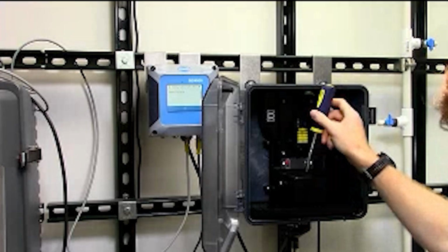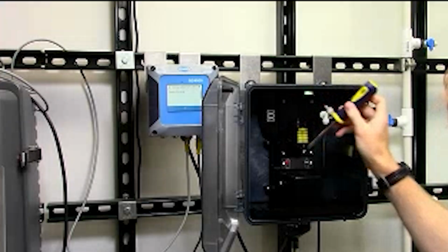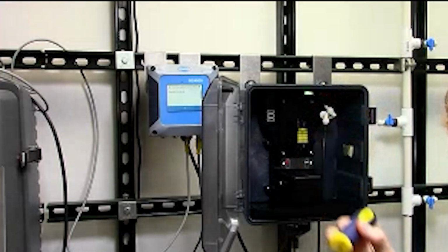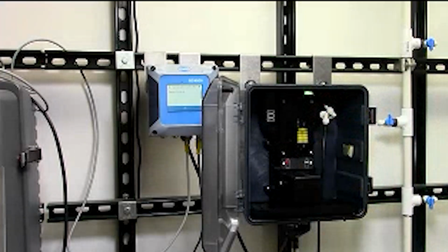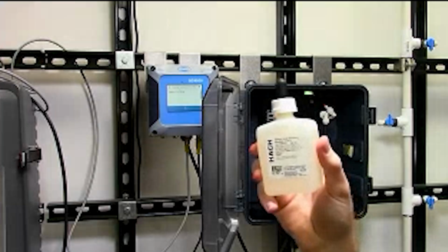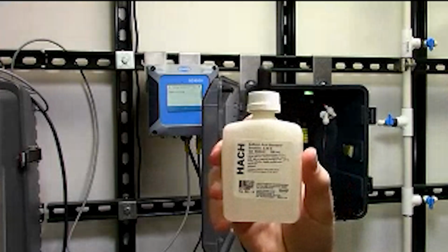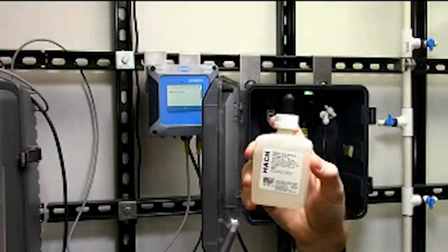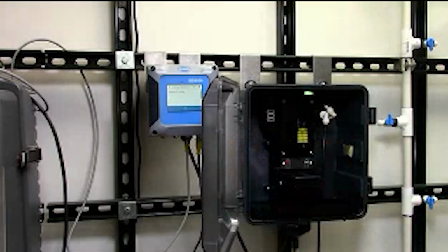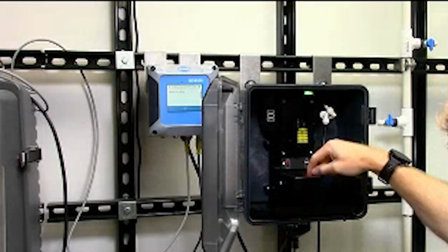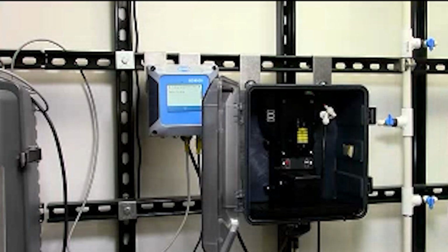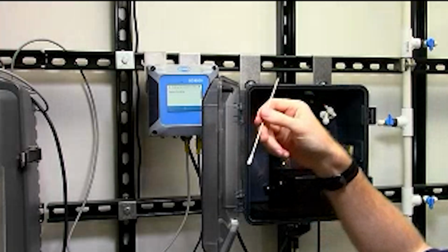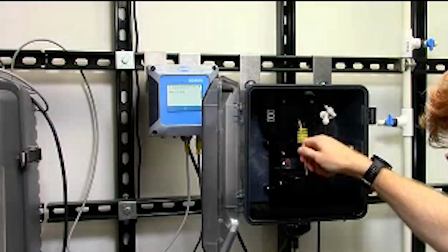Typically, I like to go ahead and remove our stir bar using something magnetic. I'm being creative and using a flathead screwdriver here. And here's when I would add in a few drops of my 5.25 normal sulfuric acid. That's going to be different compared to the sulfuric acid you're using with your legacy CL17. I would place a few drops into my colorimeter cell, and I would start then tackling each of these four